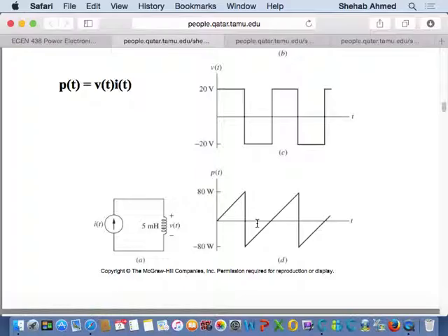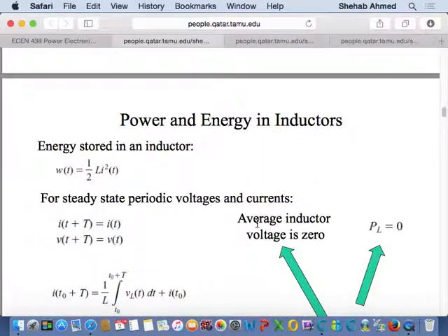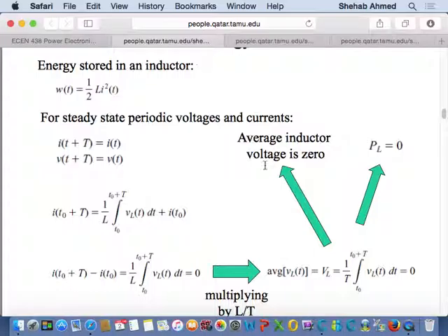But of course, this is not realistic, right? Is this a realistic circuit? It's not. I mean, any circuit will have some resistance, right? Any wire will have resistance. Any inductor is made of wire. That wire will have resistance, so it will consume power. So at some point, the energy will be dissipated, and all the energy will be dissipated in the resistor, if you have a finite energy source. Assume you have a finite energy source. So this also means that inductors look like what to a DC, a short circuit?